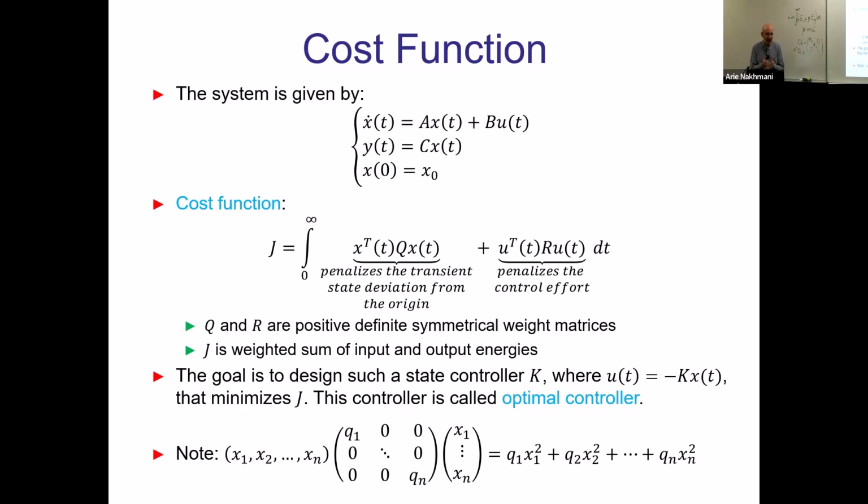It's actually not a single optimal solution; there is an infinite number of possible optimal solutions here, for different values of Q and R. But for each chosen Q and R, we will show that there are conditions for uniqueness of the optimal controller. So you have only one possible controller out of all possible controllers, which would be optimal for that given Q and given R. All right, so you have a unique solution for that problem, which is interesting in itself.